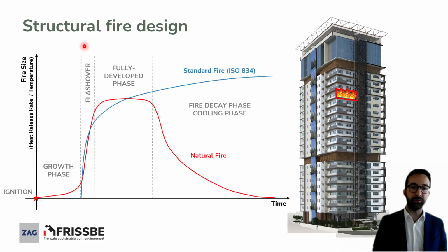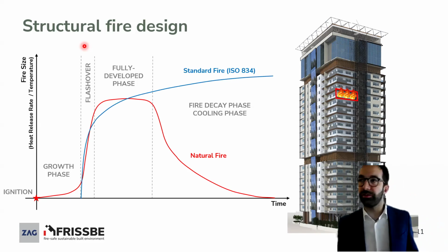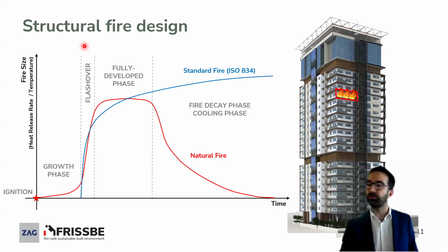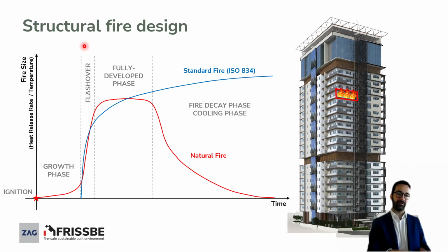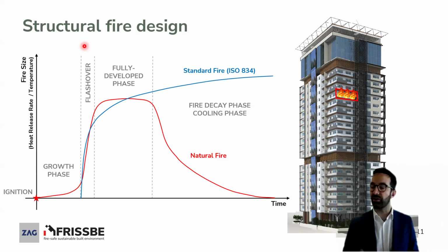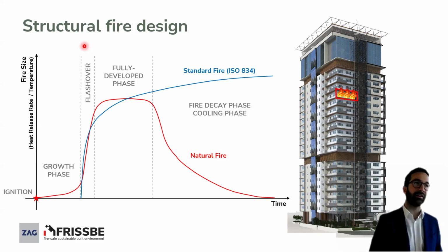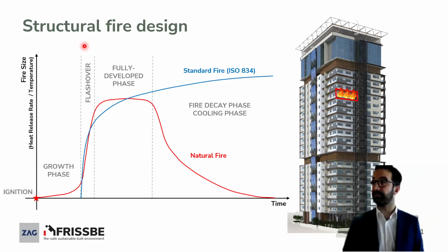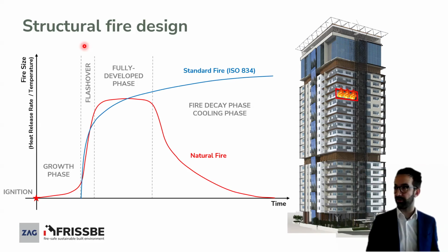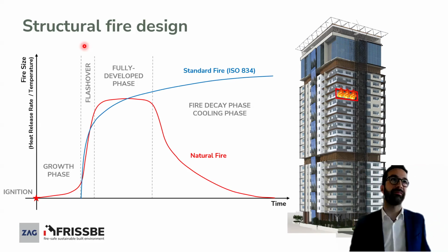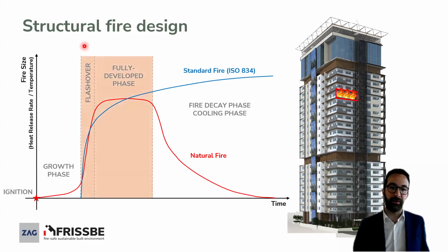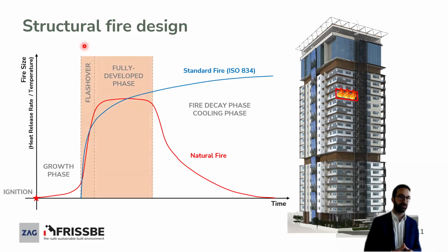What we typically do, depending on the standard and the conditions, is take a representation linked mainly to the fully developed phase of the fire, because we acknowledge with time that in structural fire engineering it is the fully developed phase where the heat fluxes and the temperatures would possibly challenge the structure through the heat insult. Therefore, we focus mainly on that part, and we specifically test for a specific duration.